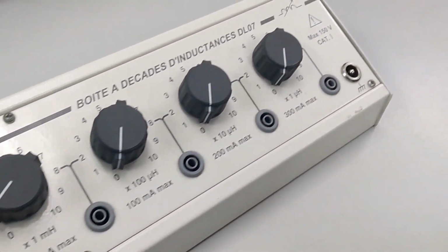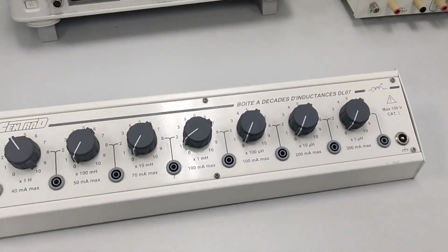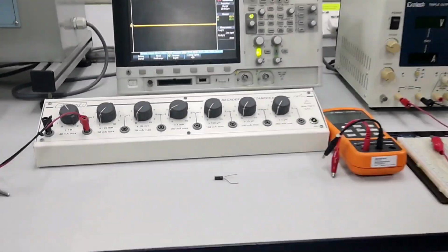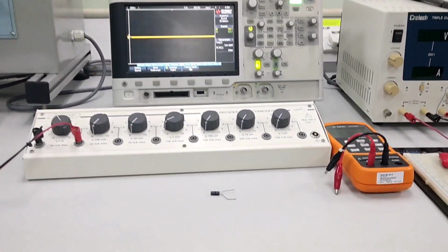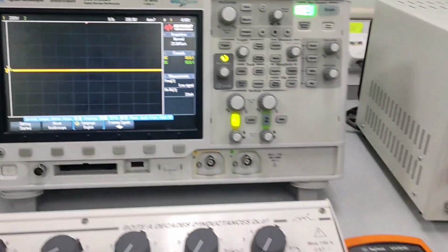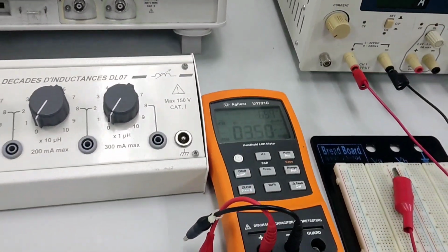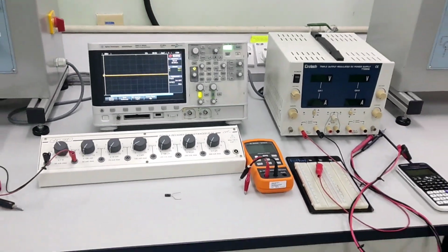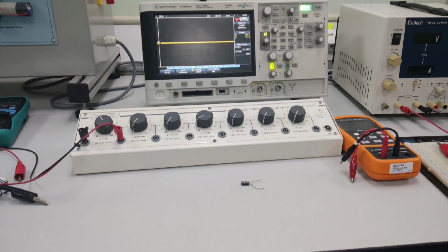We cannot measure inductance using a multimeter because it is more difficult to measure inductance than resistance or capacitance. Inductance is usually measured in units called millihenries or microhenries. It is commonly measured using a frequency generator, an oscilloscope, or an LCR meter. It can be calculated through a voltage-current slope, measuring the change in the electrical current passing through the coil.